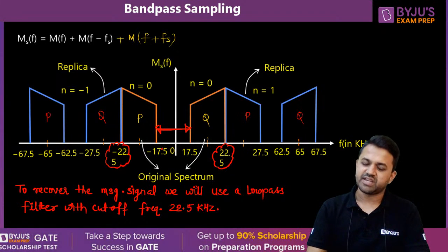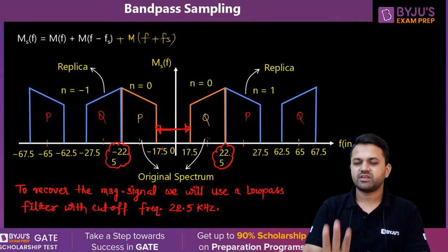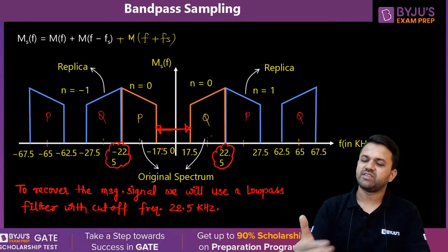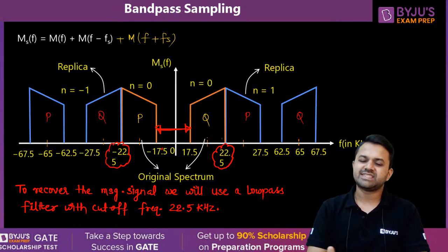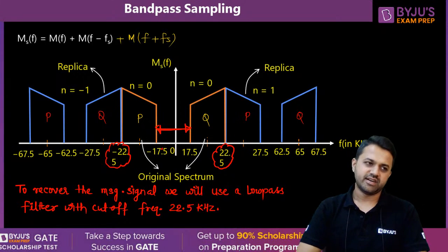But suppose if it comes, then this low pass filter allows it to pass, so that will also not give us a proper result. And if suppose there is no message signal, then it is okay, we will get our message signal perfectly, but we are wasting the range of the frequency. So that is why this type of design is not actually considered.